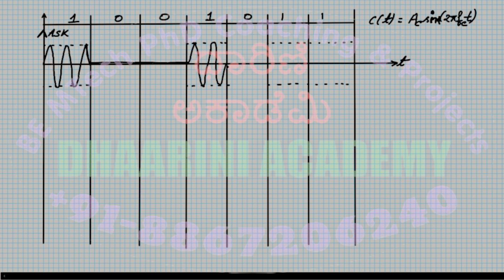right? Once again, I don't have to send, it's zero, because the bit you are sending is zero. Once again, I have two ones, which means you will pass the signal. So whenever it is one, it will pass. You don't have to change anything, simply pass. So this is the waveform of the ASK wave. Whenever zero, you don't send anything, it's completely zero, like this.